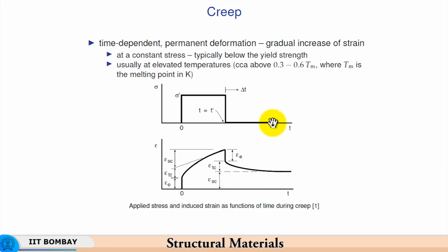Although the stress has become 0, the strain continues to remain in the material. Although after long durations the strain rate might be very small, still that 0 strain rate is asymptotically reached. So, here you see that the strain rate is relatively high, and then gradually it becomes practically 0. So, what we see here is that irrespective of whether it is loading or unloading, the strain in the material lags behind the stress. Okay? The strain response lags behind the stress response.